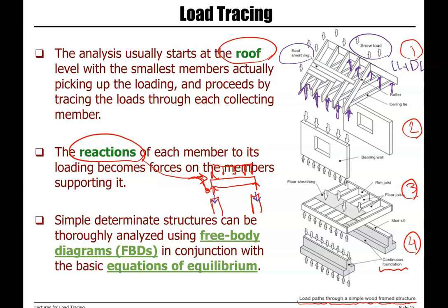Reactions are the forces transferred to the next element, the element supporting our roofing system. Bearing walls are supporting our roofing system. So the same magnitude with the opposite direction is transferred from the roofing system to bearing walls. So the reactions that we see in our rafters are the loads applied to our bearing wall. Then we need to